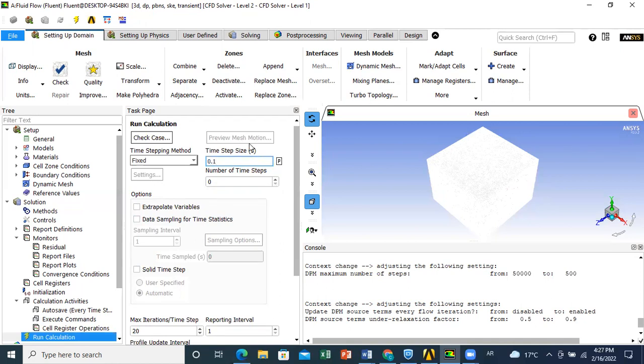And the selection of time step, we will also discuss in the course material, how to select a time step that will allow you to have convergence, okay? The time step is very critical to have convergent results. So sometimes if you select a very large time step, you will have divergence. And also, if you make it very small, it's not very good. So we'll see how to optimize this time step for certain problems.